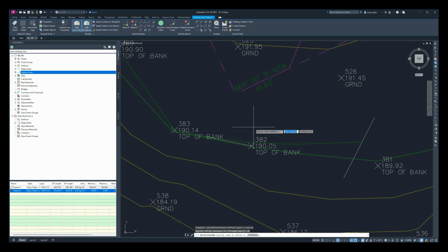So that's going to be clicked on screen. Let's go ahead and hit south of our feature line, and then we're going to be asked to give a surface depth, an elevation difference. Let's go ahead and put -10, press enter.